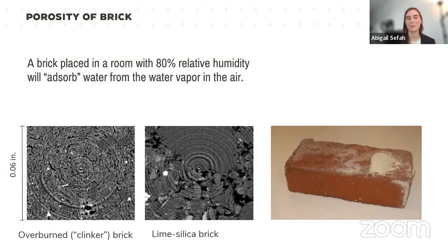A quick note on the porosity of brick. If you put a brick into a bucket of water, it will absorb water, and that's called absorption. But if you leave a brick in a humid room, say 80% relative humidity, it will adsorb water from the air. And so it has these pores that, if it's dry, the pores will be empty. And if you leave the brick in a humid room, then those pores will get full of water from the humidity in the air.